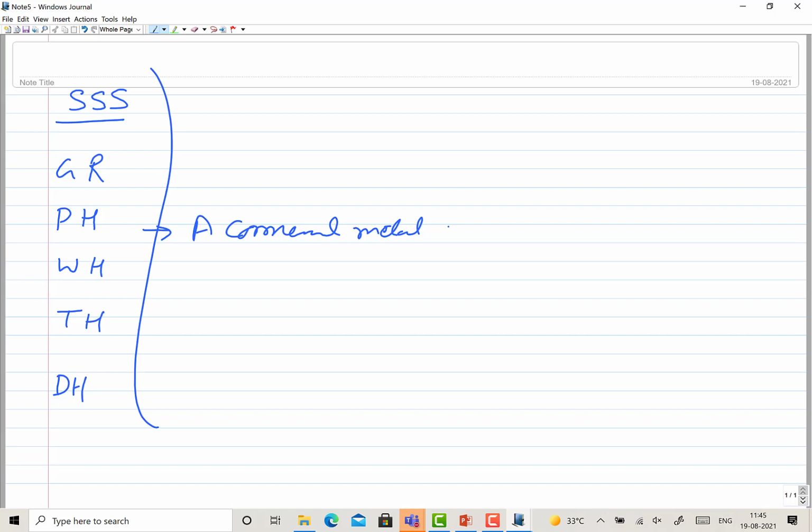Okay, so although relative importance of other mechanisms may be marginal, say you know that a simple carbon steel system, they gain strength from the interstitial solid solution of iron and carbon, right? But you also know that if the refinement is taking place, then it increases the strength, say from 350 to 400 MPa. So there is always change in the properties.